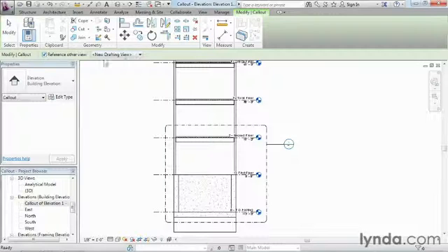If you put a check mark in Reference Other View, it's going to allow you to reference another view that might already be in the drawing, such as maybe this callout actually exists in 2 or 3 other locations. It has the exact same detail, the exact same conditions in all those other locations. If that's the case, there's really no reason to keep creating new views based on that callout. All you have to do is put a check mark right here and then pick that other view that's just like this one you just created, and it'll automatically point itself to that view as opposed to creating a new view from scratch. So that's the idea behind referencing another view.